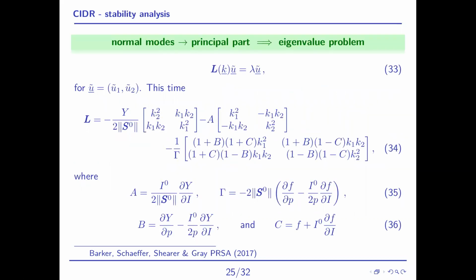So this top green line is summarizing that same process that we used for the incompressible case. I'm not going to focus too much on the details. Again, we've still got three variables. Instead of the pressure now, it's the two velocity components and the volume fraction. In fact, we kept the pressure as an extra possible dependency to see how that all filtered through. But in any case, we've been able to do some other trickery, not exactly the same tricks as last time, to reduce everything again to a single eigenvalue problem in terms of just a velocity perturbation.